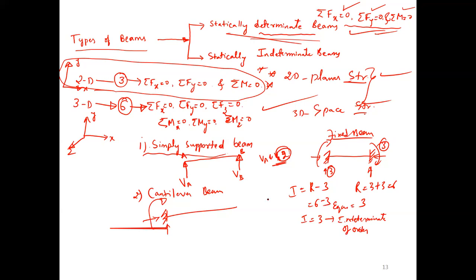I will give one more example. You know the propped cantilever beam. One end has a simple support, and the other end is fixed. Now tell me how many reactions, which order it is, determinate or indeterminate? Try it. Propped cantilever. First degree order, so indeterminate.